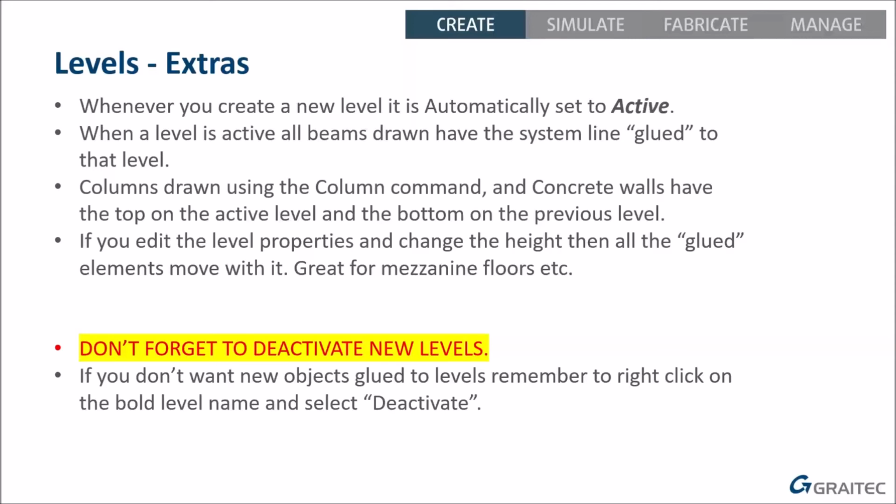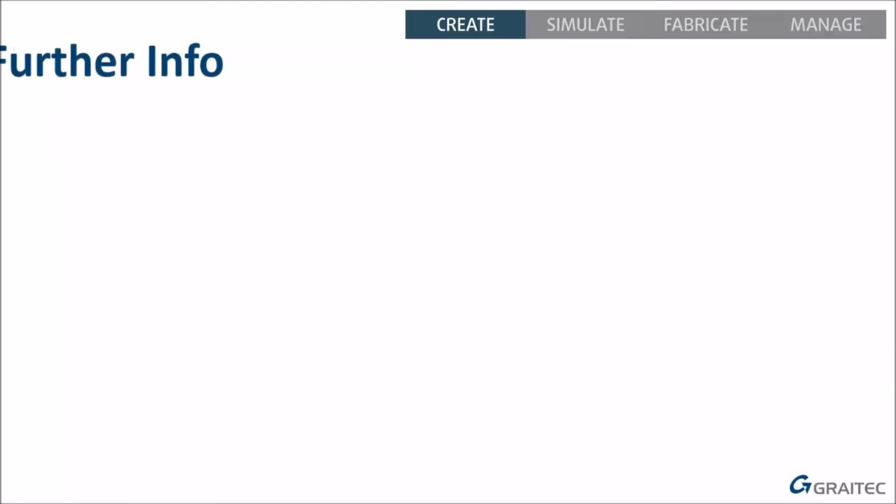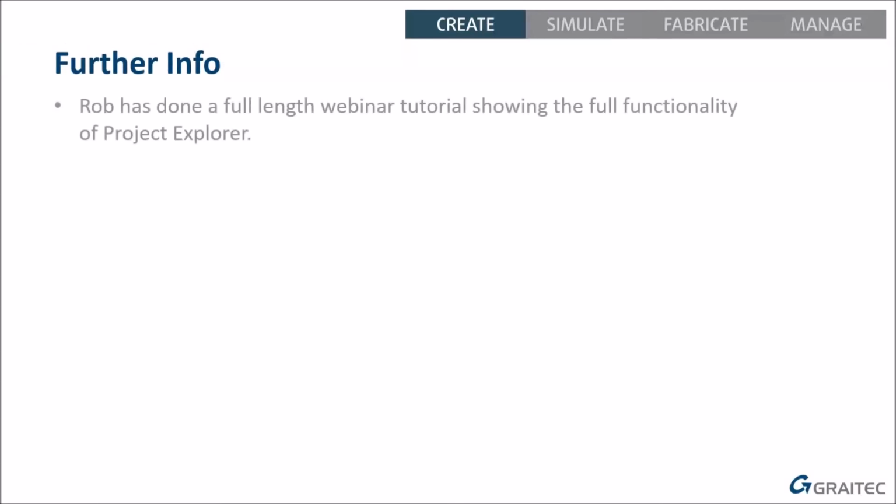And then you do level 2, so you set up level 2, and you go again, click, click, click on the same snap points from the ground, and you know it's going from level 1 to level 2, and all the horizontal beams are on level 2. Really fast, really easy. So that was a very quick whistle-stop tour.